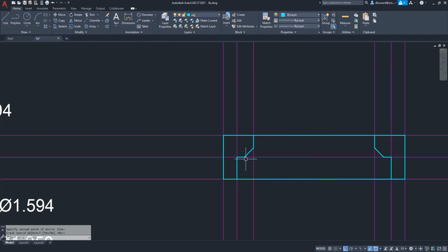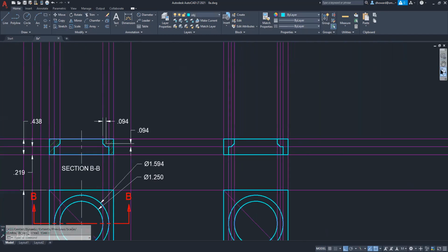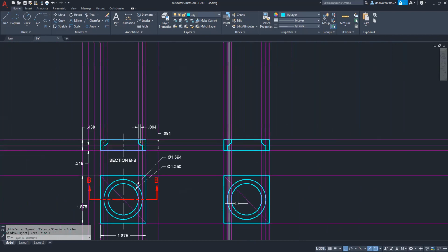We do need to show this chamfer in the bottom view. So I'm going to do that by projecting a construction line down from that corner and then zoom out here and draw that ring, okay? So that should be a ring that's simply offset by 3/32, and that would be another way to do it. O, enter, 3/32, and click on this guy and say, yeah, it's 3/32 bigger, and that worked.